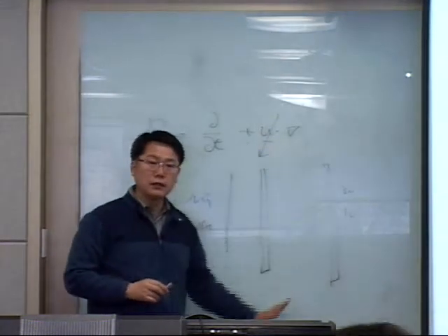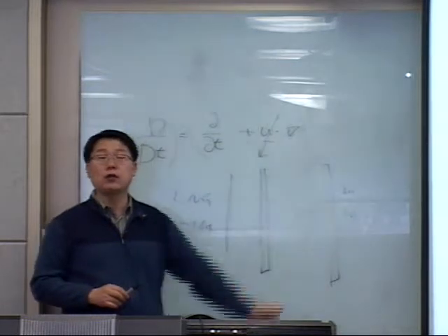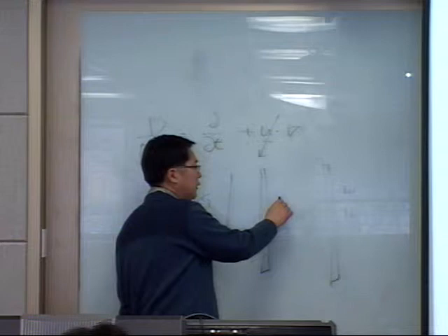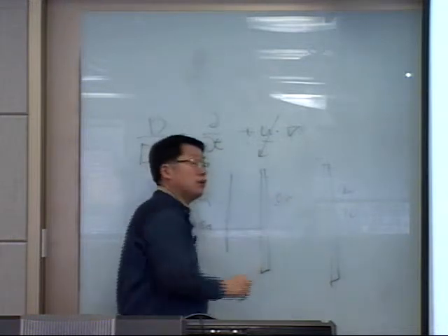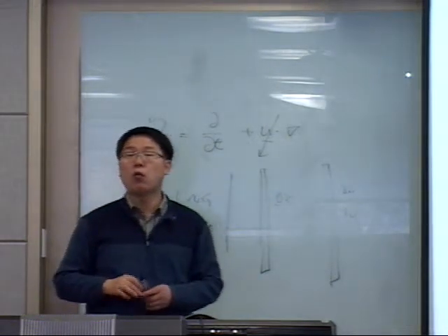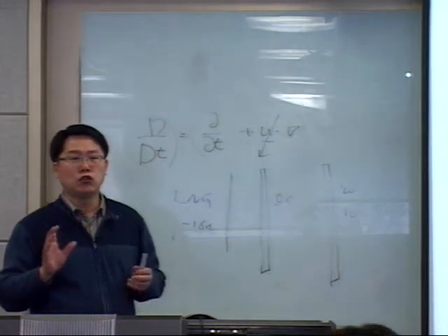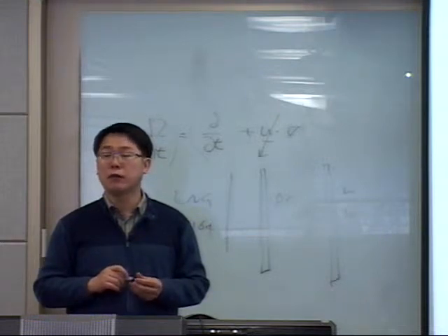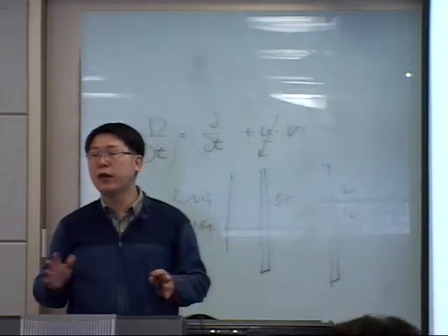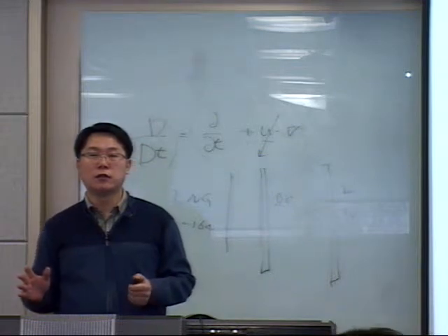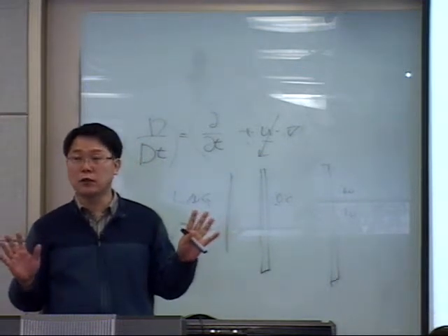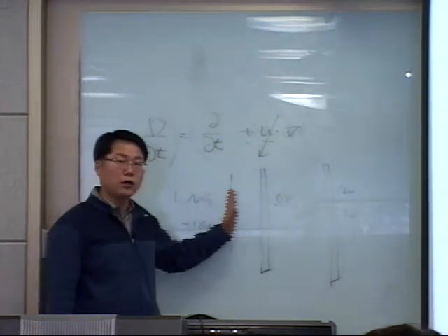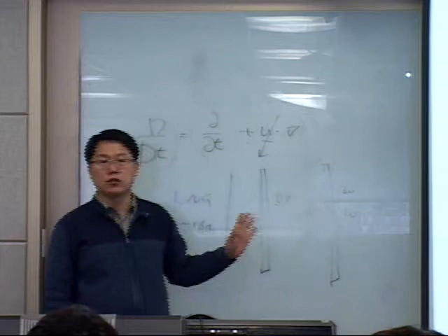Since we have a void space here, the boundary condition is usually put at 0 Celsius. What is important is that you should know the detailed structure of the cargo containment system and the neighboring structure. The boundary condition itself is not important. What I mean is that you should know the inner structure of the ship.